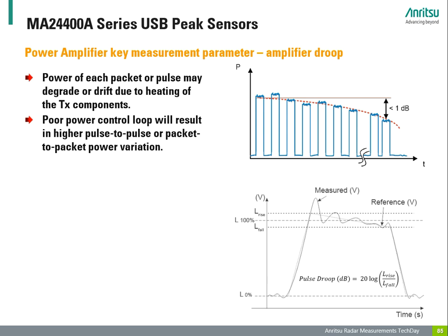In high-power transmitters, such as Klystron amplifiers, it is unable to maintain full output power during a long pulse, which results in pulse droop. In solid-state power amplifiers, the primary cause of droop in gallium nitride power amplifiers is the thermal response of the transistor.